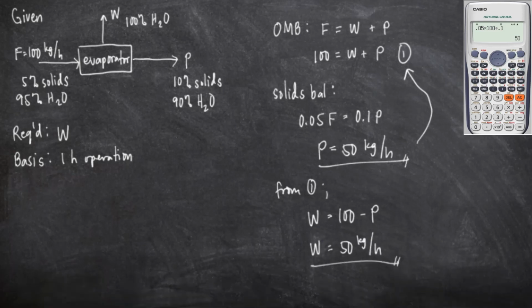That is how you perform the material balance for evaporative processes. Take note that this approach carries with it its own set of assumptions. That is, the evaporate is pure water and that we can lump everything that is not water in a category known as solids. This form of the diagram is also applicable for direct heating dryers, wherein you have a wet feed and then you pass it through a dryer to get a dry product and the evaporated water or moisture.